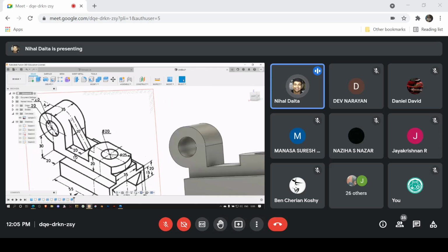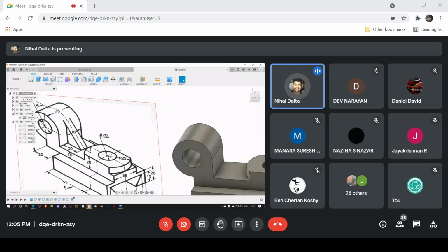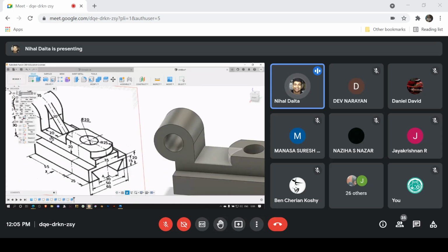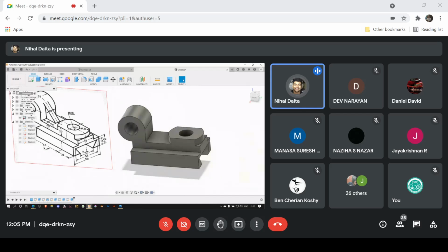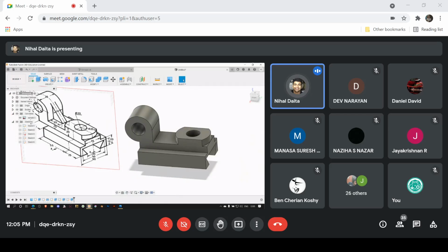So basically what you need is a single reference line which marks the exact point where it would occur. Basically, you see this dotted line. This is what we are going to replicate as the sketch for our rib. So it says it's 20 units, I guess. We'll just say it's millimeter, it's fine. It's 20 on horizontal axis, and it needs to be tangential to what this thing is, right?